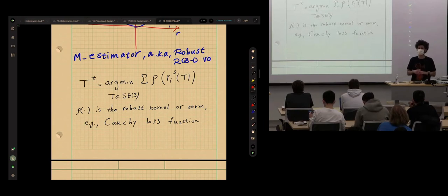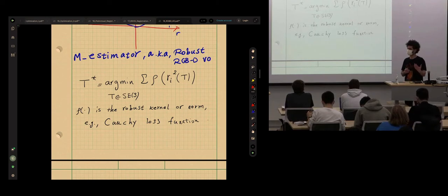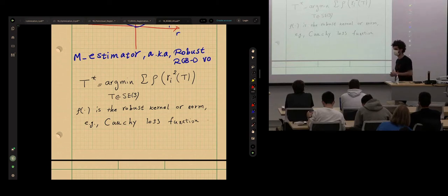Indirect methods are better when the transformation is large. Indirect methods are also very good for solving non-temporal registration problems. In particular, in loop closure, when we detect the same place, we see the same place from a completely different angle. It's challenging for direct methods to solve the registration problem because the initial transformation is very large.